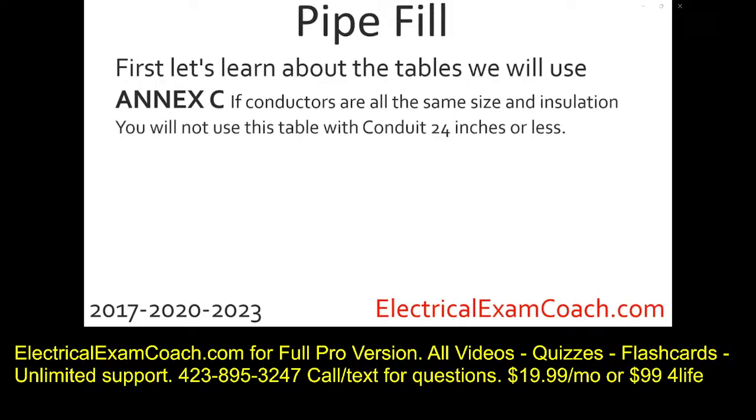You will not use this table if the conduit is 24 inches or less. Now, the code book uses the term nipples, but I want you to imagine in your mind, anytime the conduit is 24 inches or less, you're not going to use Annex C. You're going to use the method that I'll teach you in lesson 7.2. You can head to page 712 of the 2017 and page 729 of the 2020. This video is 2023 compatible. You'll have to get to your page number for Annex C, and then you can follow along.